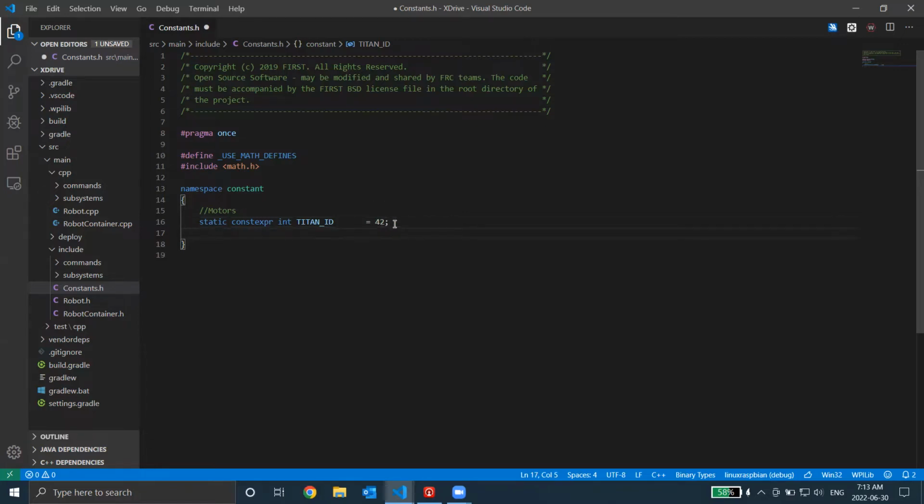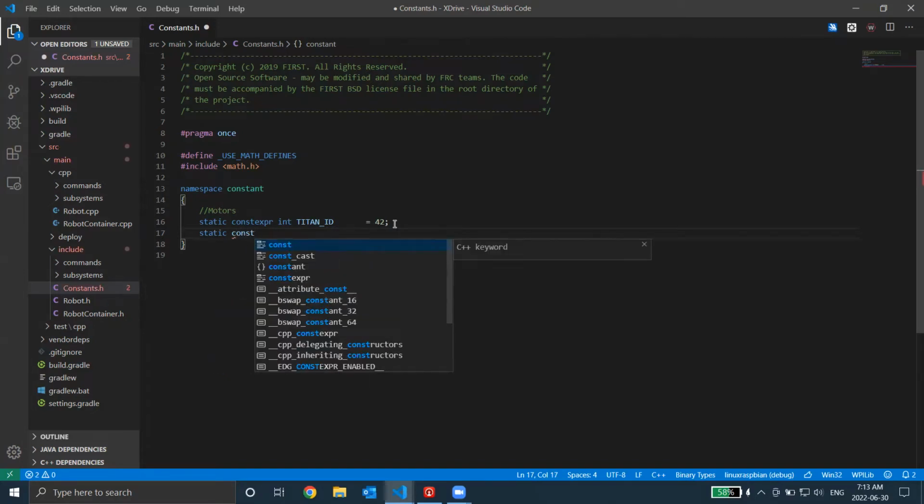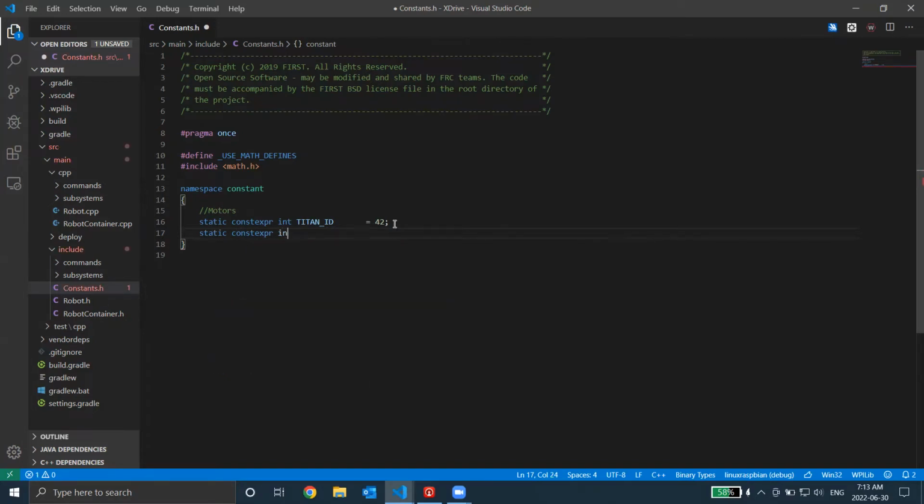And now I can map out each motor on our robot. If you remember, our robot's using 4 motors because we're doing an X drive. I'll call the front left motor front left because that seems pretty obvious as to what it is. And the motor port for that is M2. So I'm going to put 2.